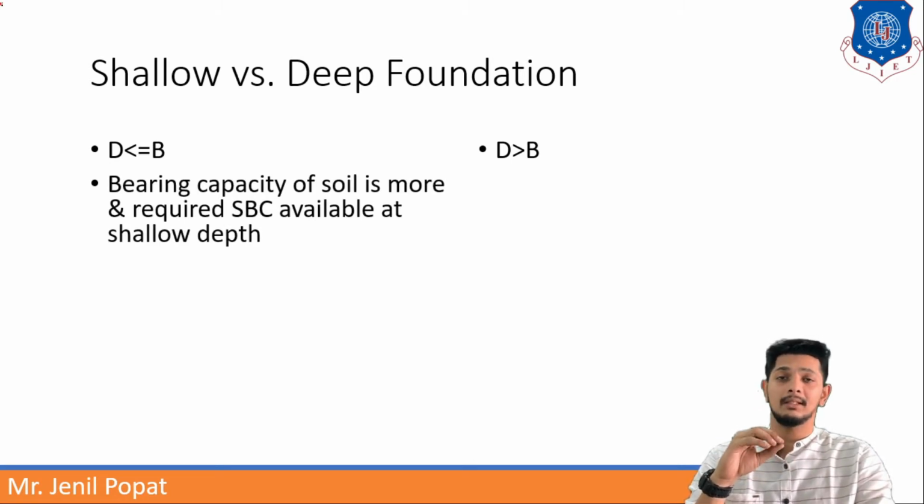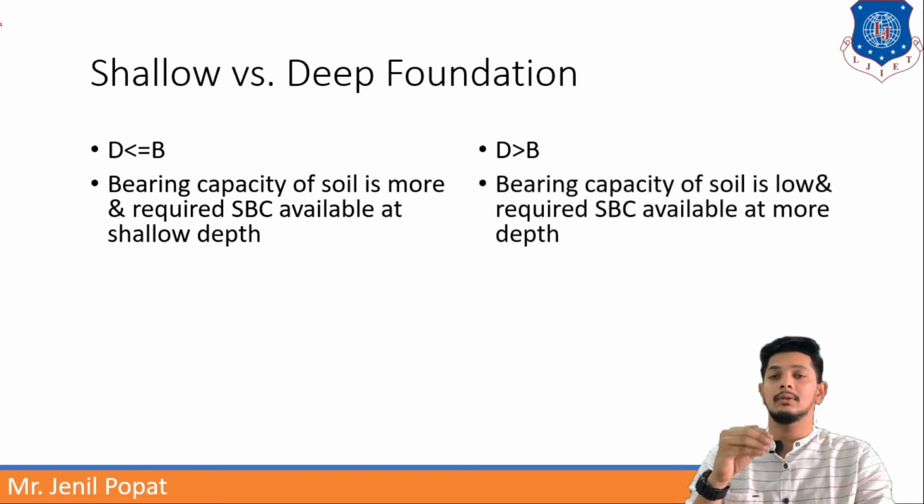If the bearing capacity of the soil is more, and the required soil bearing capacity, SBC, is available at shallow depth, I will construct a shallow foundation. And if the bearing capacity is low and the required SBC is not available at shallow depth, you need to dig to more depth, then you will provide a deep foundation.